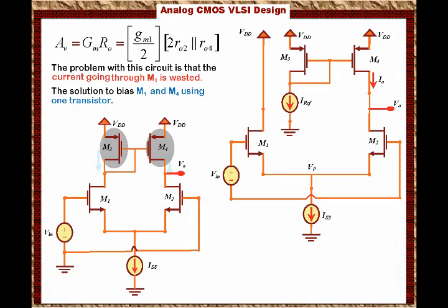Then always I3 equals I4, right? This is the requirement we have to have. Otherwise the circuit will deviate and you will have some problems, right? Because the current ISS must be split in half between M1 and M2, and then the currents through M3 and M4 should be equal. Then we have to say that M3 and M4 are mirror images of each other.